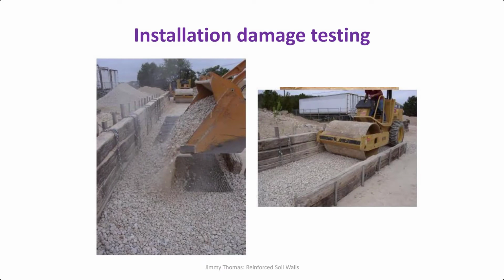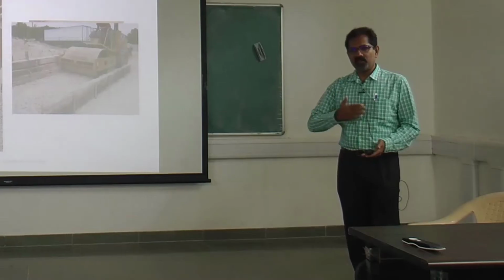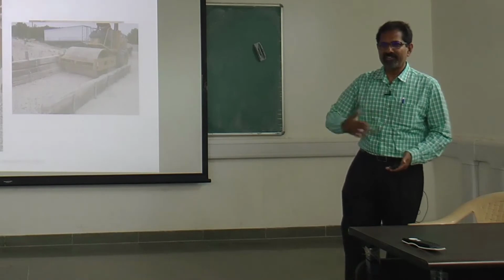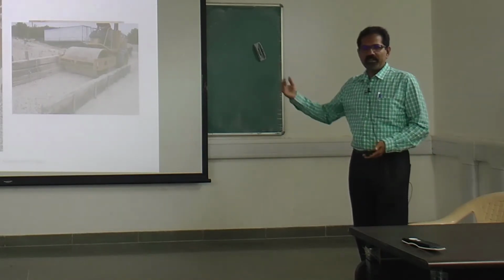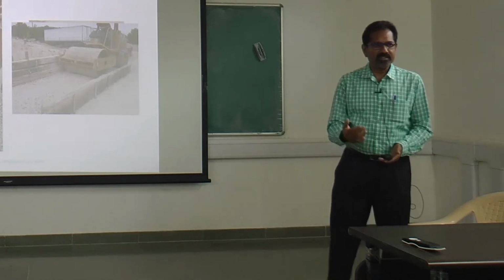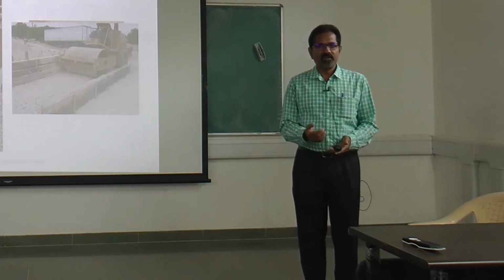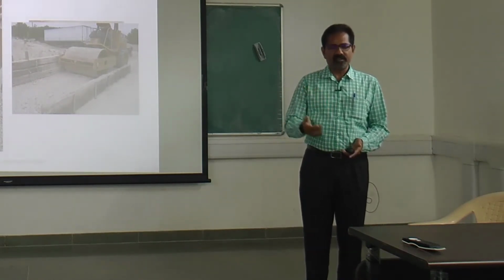Then another factor is installation damage. Like during construction, we place the reinforcement, we put a layer of soil over that, then it will be spreading, grading, then with the rolling. In that process, the reinforcement may undergo some damage. So its strength will reduce actually. So again, I have to factor that into design.